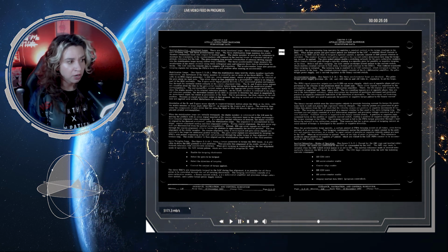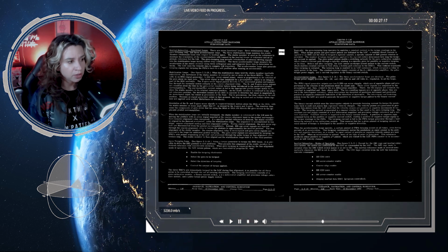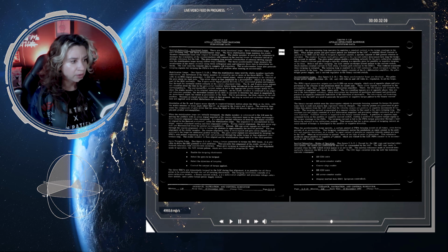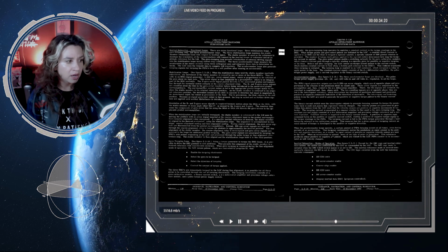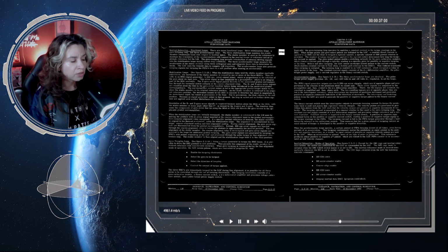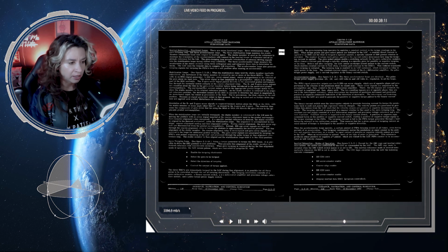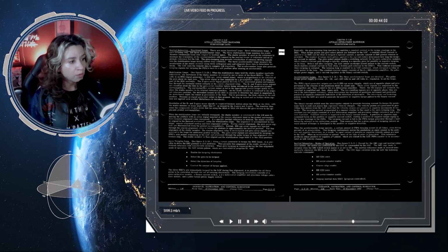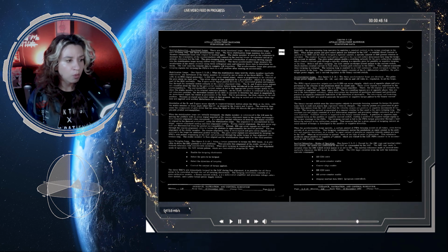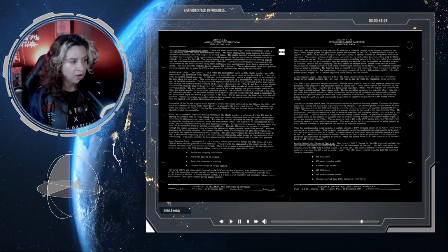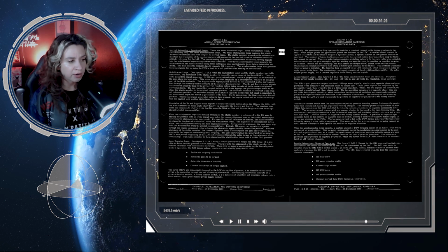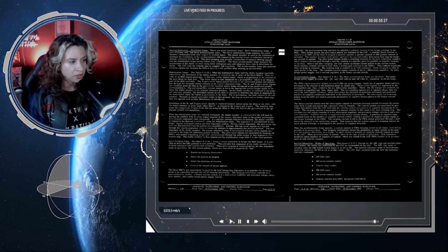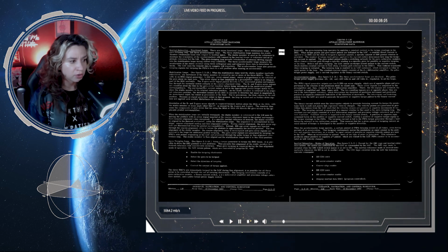1. Enable torquing electronics, 2. Select gyro to be torqued, 3. Select direction of torquing, and 4. Control the amount of torque applied. The 3 IRIGs are sequentially torqued by the LGC during the fine alignment. It is possible for all 3 gyros to be controlled through one set of torquing electronics. The torquing electronics consist of a gyro calibration module, a binary current switch, an ADC differential amplifier, a precision voltage reference module, and a pulse torque power supply module.